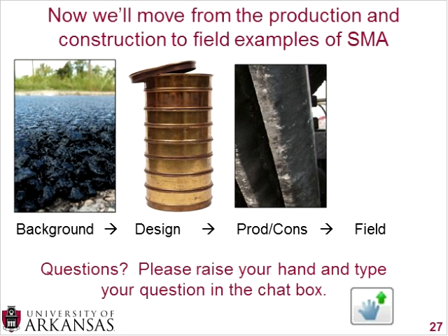The next question is from Jay, and he asks, are there any changes to the mix design when SMA is produced using warm mix technology? Now that's an excellent question, and if I pull out my AASHTO standards, which I'm actually literally doing right now, they were both put out in 2008, these 2 AASHTO SMA standards, and they have no wordage in here about warm mix asphalt.